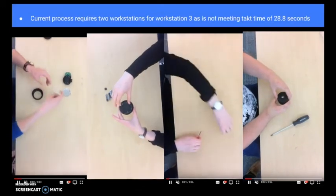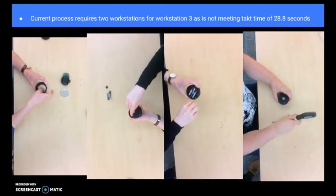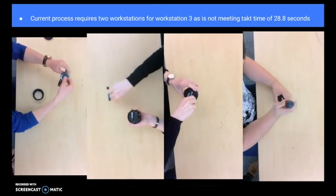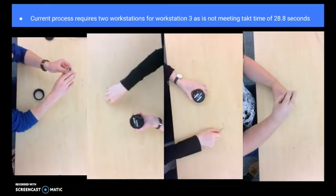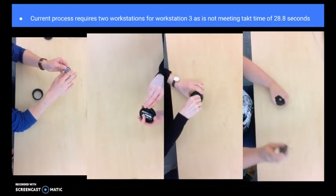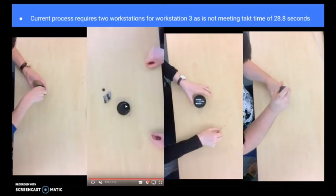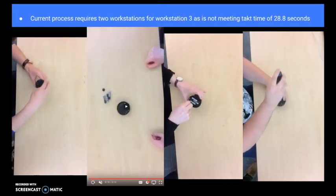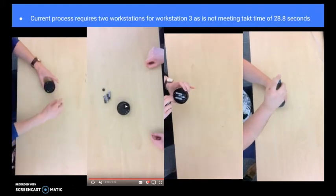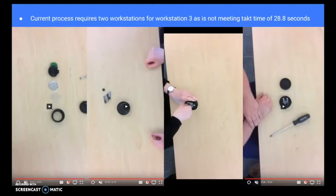So these videos show the current process that's in place. As you can see, they're all happening simultaneously to show what would be happening in the assembly line. This is supposed to have a takt time of 28.8 seconds, but as you will see, workstation number 3 exceeds this takt time and therefore requires 2 workers to do this task.